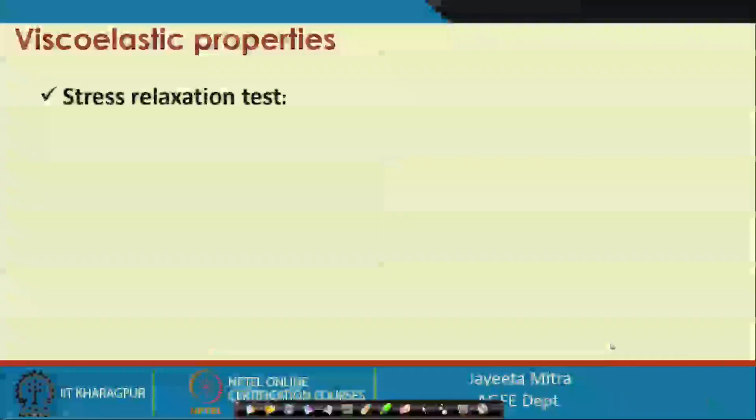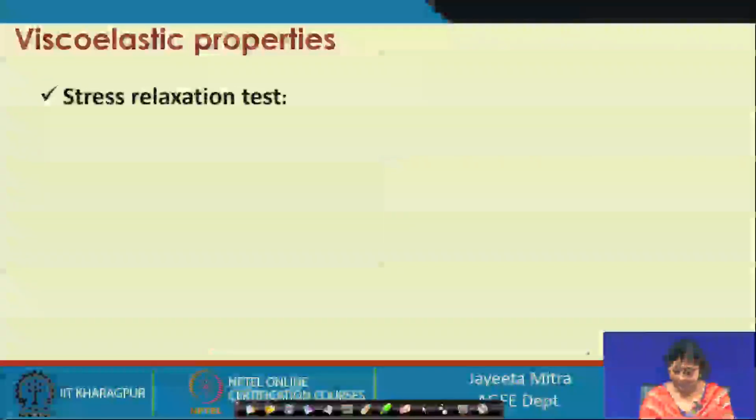Stress relaxation test. Now, what is stress relaxation? If we apply constant strain on a viscoelastic material for a prolonged time, then with time the stress required to maintain that strain will die down, or decrease gradually.